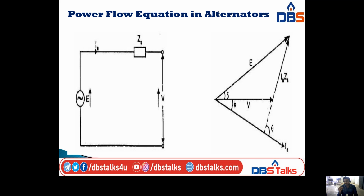After that I draw the EMF line E, leading the voltage line, and the angle between V and E is delta. We have the voltage drop IAZS, the synchronous impedance drop, and that line is parallel with the voltage phasor line.